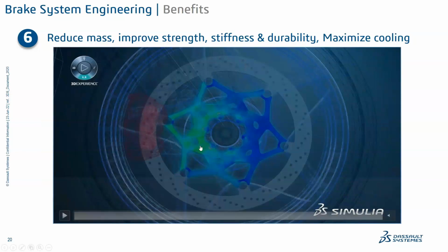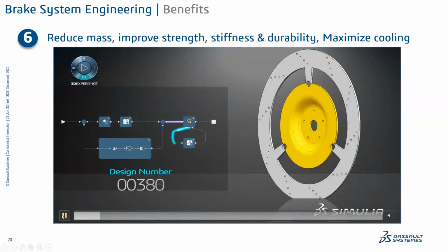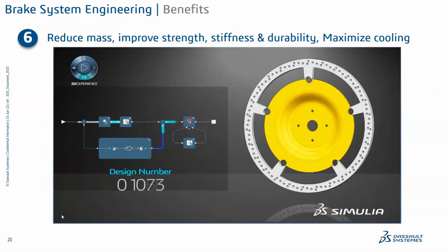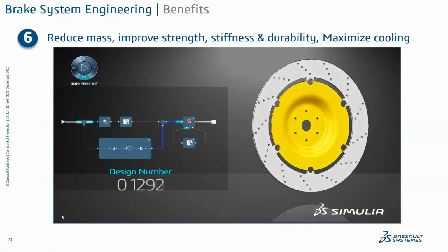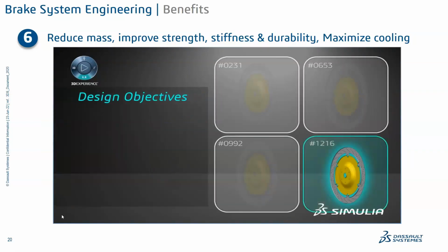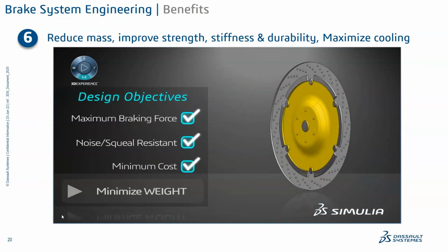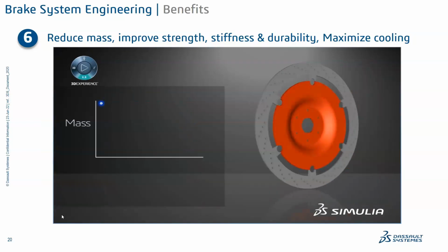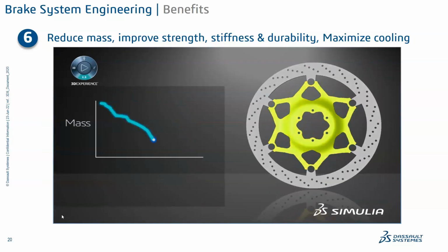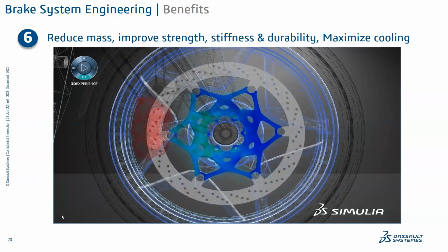If you see here, a complete workflow has been automated, starting from parametric designing, parametric optimization, and understanding the fatigue and the life of it, and redesigning your brakes accordingly for a better life, and also a non-parametric optimization to minimize the weight, and everything has been validated.